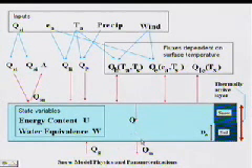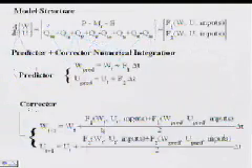And then at the bottom of the snow, there's perhaps meltwater outflux that is presumably infiltrating into the ground, although it might be running off beneath the snow. And you also have some ground heat flux. We keep track of state variables that give the energy content and the snow water equivalent of the entire system, snow as well as the soil, over an effective depth. And our model is primarily going to be concerned with how those state variables advance or change in time.